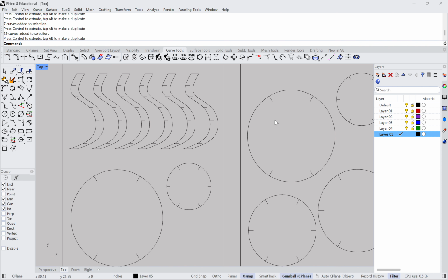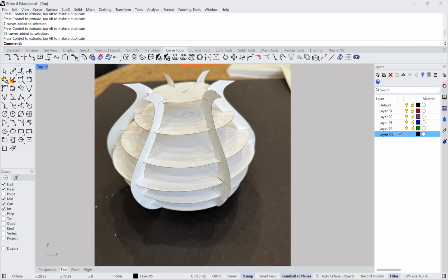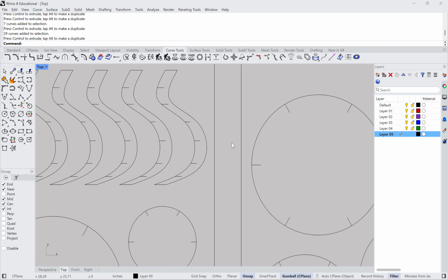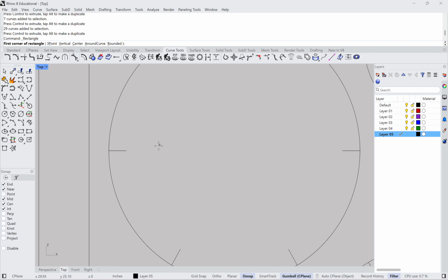We're doing this for the very first time, most of us. And I would rather keep our design ideas simple. That way we understand how the manufacturing process is really going to work. Let's say that you want to try doing the same sort of simple in the round idea, but out of wood. The difference there is instead of a single line, you're going to want to create a rectangle, the thickness of which matches the thickness of the material you're going to be cutting on.